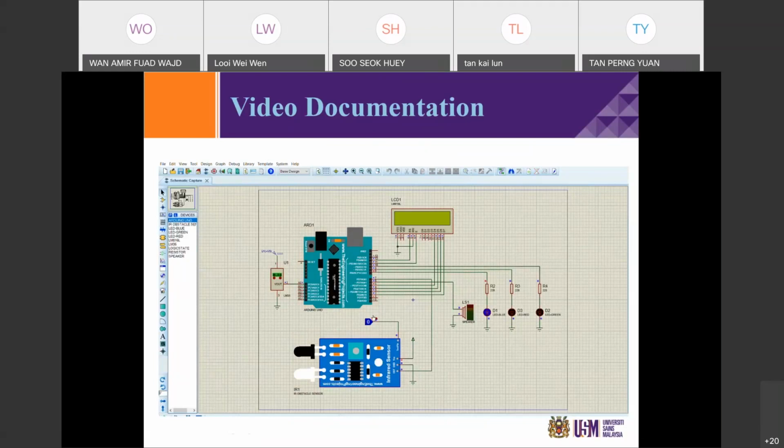Firstly, set up the circuit as in my simulation and run it. The infrared obstacle sensor will start to detect the people, then has a test pin to represent the presence of people. When the logic state of the test pin is 0, all components in the circuit will not function except the blue LED. The blue LED will show high output, meaning that the system will be temporarily down and in saver mode to consume less electricity.